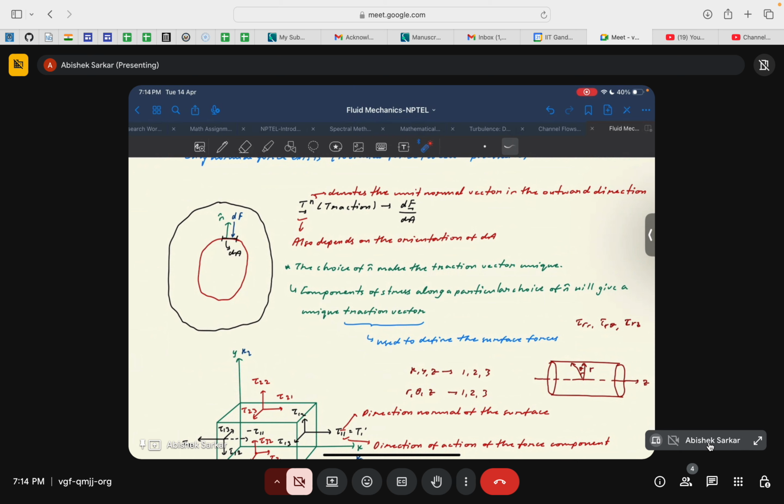Yeah. So the traction vector was formally defined to club together the contribution of the shear stresses and the pressure forces. Okay, so in the case of a fluid at rest, that is, fluid statics, the only forces that exist in the flow domain were the pressure forces and of course the body forces. The surface forces that arise in fluid statics were only because of the pressure forces, and you will see the traction vector eventually boils down to the pressure force.